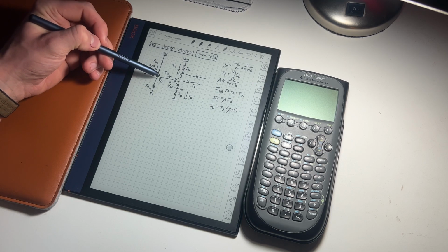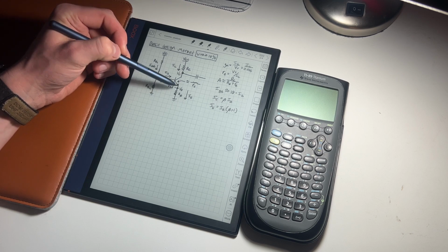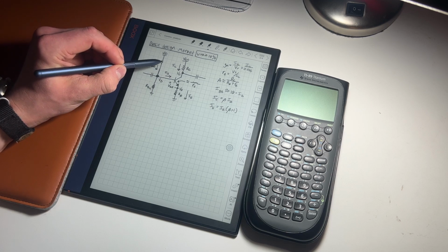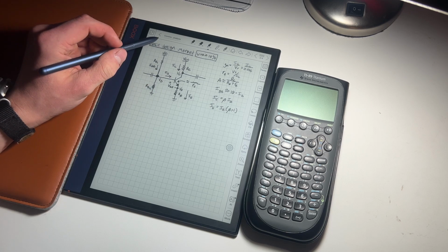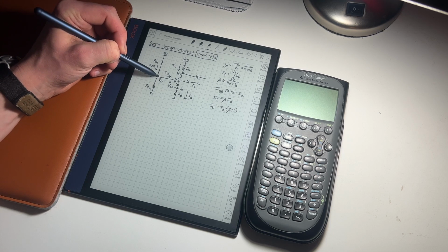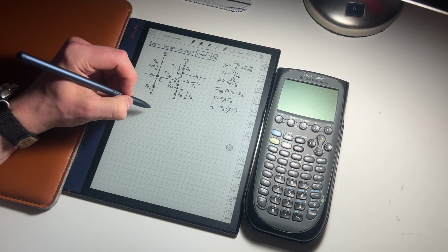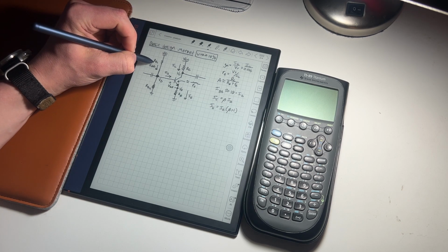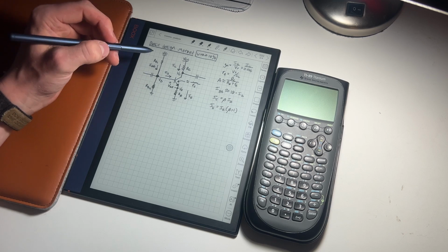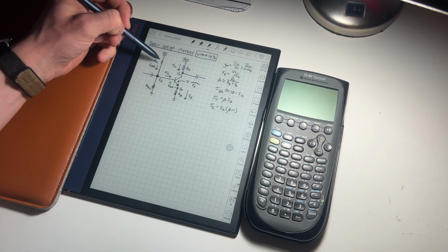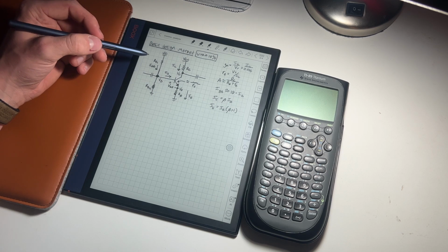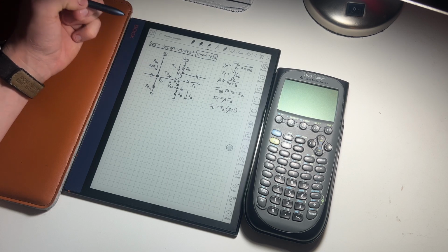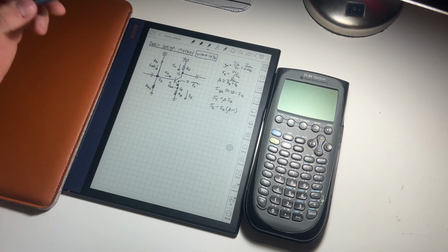Now with that you do have current running through the base, which when you're setting up your voltage divider here will start to steal current from the divider. So to keep the voltage at this point on the base relatively stable, you want the current that's flowing through RB1 and RB2 to be larger, or much larger, than the current that will be running into the base during operation. This will keep the base voltage very stable and will allow you to have a very stable output.